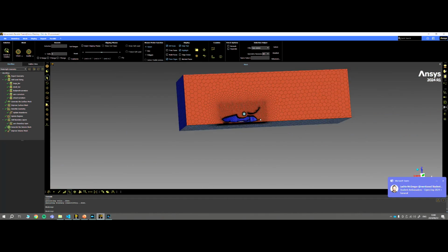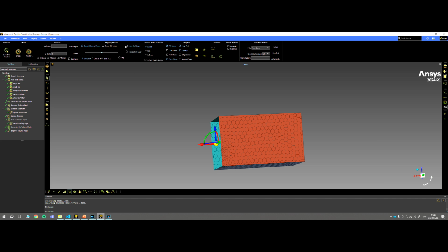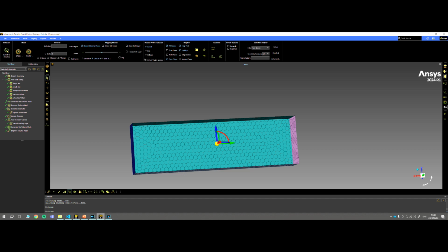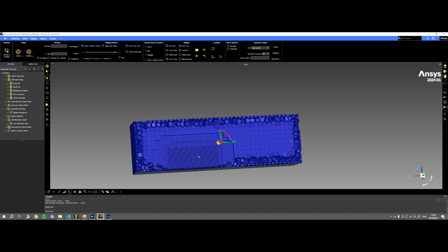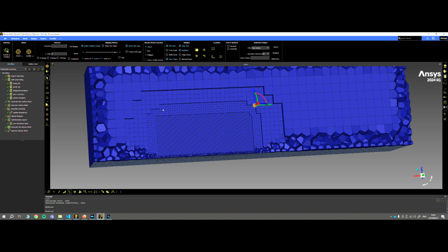And then another feature of Fluent is you can insert clipping planes. We can change which direction it is in. Do it in Y, and then we can draw the cell layer and move the area. So there we can see the difference in cell size between the small body of influence, the large body of influence, and the enclosure.